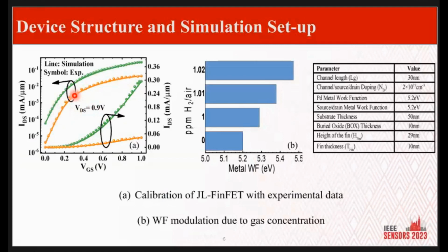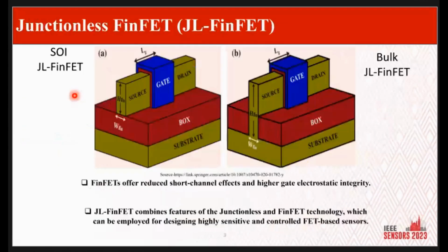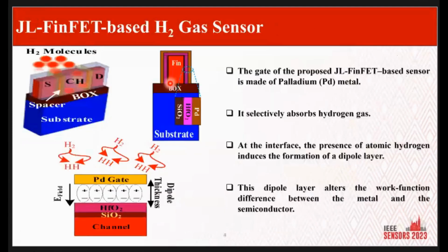So if you make a device, and any device now that you have in your phone, the gate is metal on the top. So this guy here is metal, right? Can you see it's metal? If you make metal, usually it's copper, because you cannot make a uniform coating layer of this copper metal, usually you have grains, and these grains have different work functions. And because they have different work functions, they pin the Fermi level in a different place. And because you pin the Fermi level in a different place, you have a variability depending on the size of the work. So what you do here is very similar.